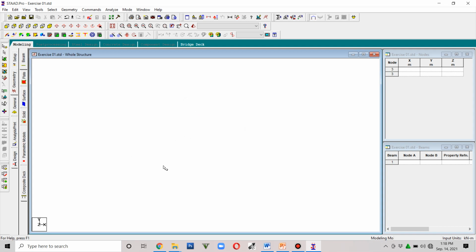So we are going to create the truss along the XY plane. Okay. So X is going horizontal and Y is the vertical. Z is the axis perpendicular to your screen. So the important thing here is you should set your nodes all positive. So do not ever have a node with negative coordinates because later on it may encounter errors. Okay, so first 0, 0, right? 0, 0. Okay, so that's the node.